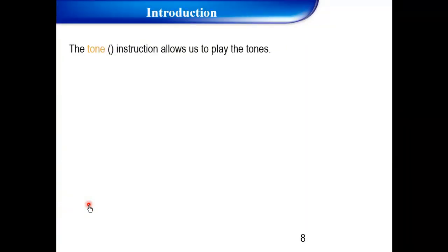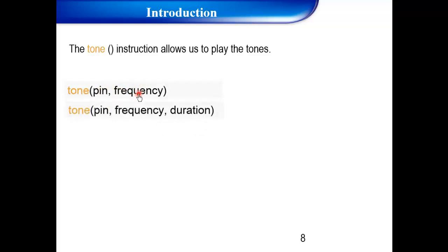The tone instruction allows us to play the tone. The tone generates a square wave. Write tone(pin, frequency), the pin of the buzzer and the frequency. We will talk about this. You have two choices: the tone function, tone(pin, frequency), or tone(pin, frequency, duration). I will talk about this.